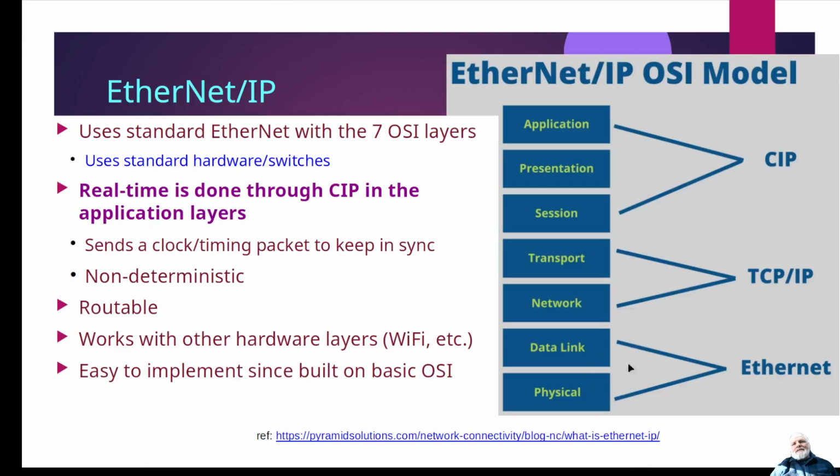again, Ethernet was designed not to be real time. However, Ethernet is so fast that they run the clock here and they can reliably do real time down to 1 millisecond. Again, they can't go as fast as EtherCAT, but they can go fast enough for 95% of all applications. EtherCAT comes into play when you have things that are extremely high speed, and Ethernet IP isn't fast enough.